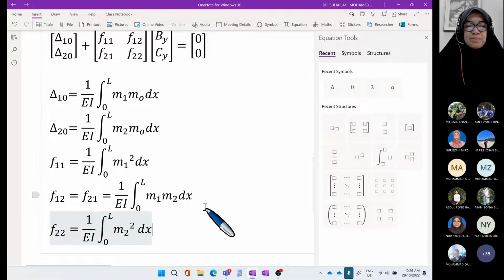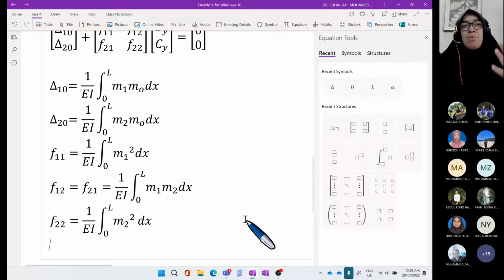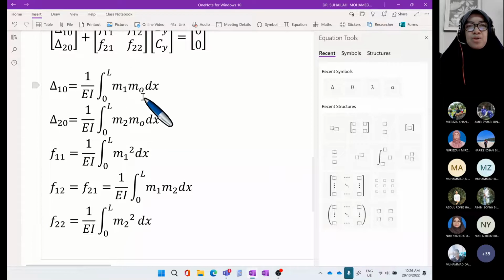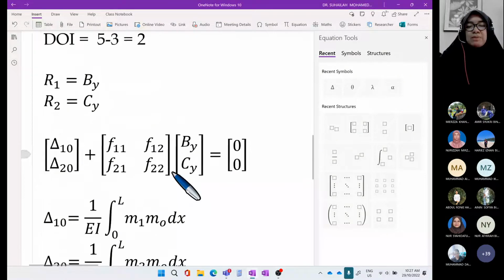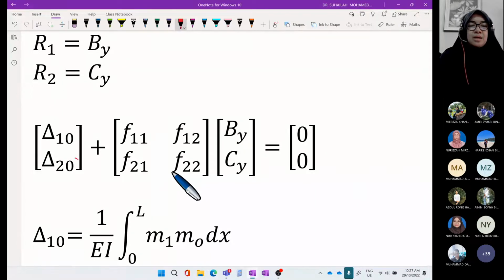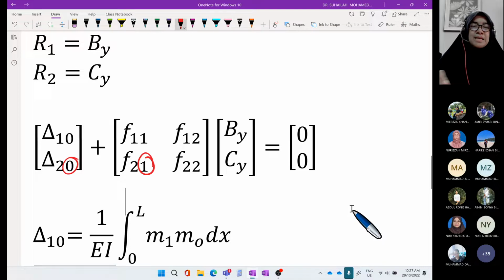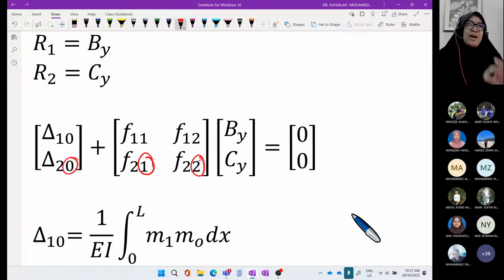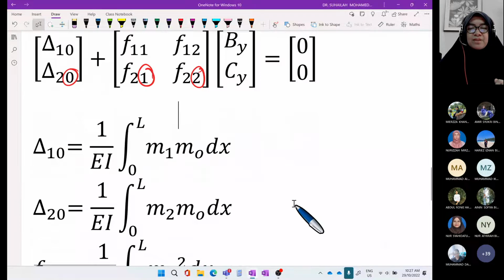So these are all the six displacement formulas. Inside these, we can find that there are three levels of moment equation: M0, M1, M2, same as I mentioned before. There are three systems. The first system is the primary system. Naught is always the symbol for the primary system. Redundant 1 is redundant BY applied. Redundant 2 is redundant CY applied. So we have three determinate systems.